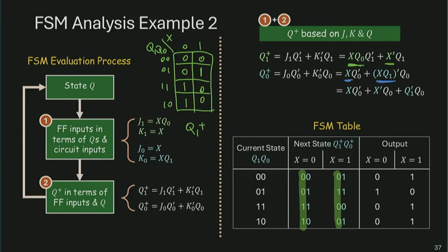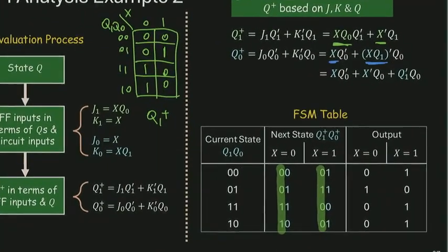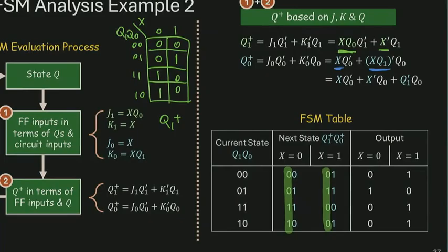We can do something very similar for the second function. Well, actually, you can also do that directly in place within this K-map. Right, I'm going to illustrate where these three implicants sit in the state table. So X equals 1, Q0 equals 0. That's the top and bottom implicant. X equals 0, Q0 equals 1.